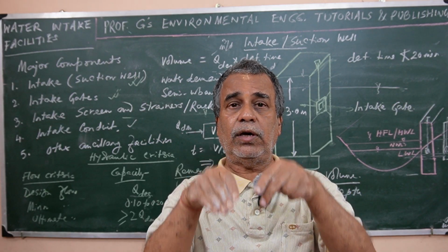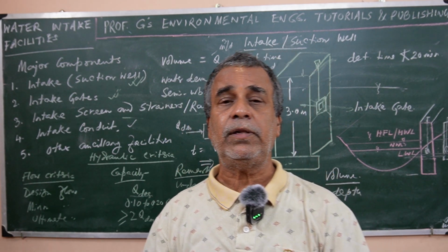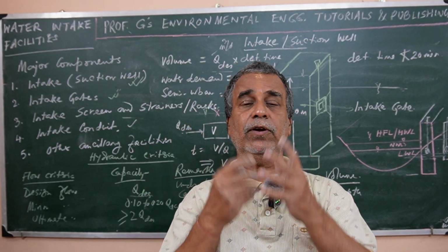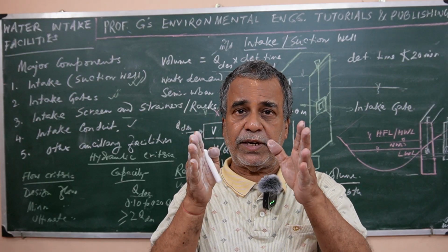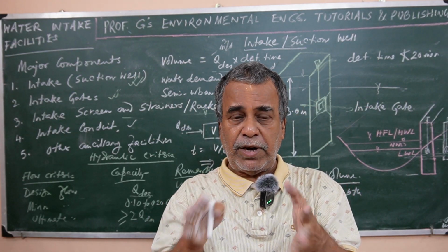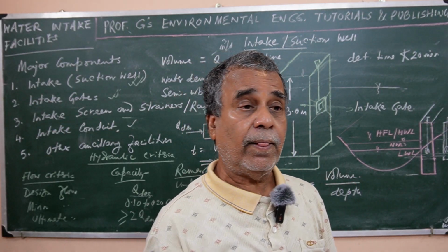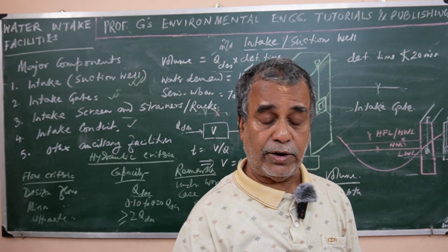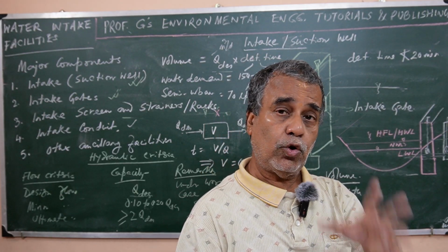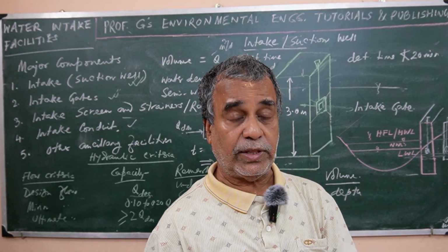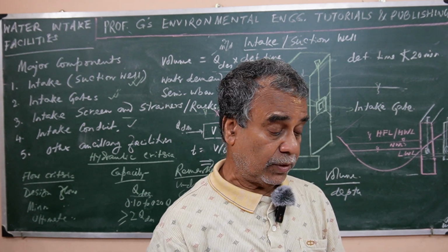So to safeguard against possible buoyancy or uplifting of the structure, the total weight of the structure must be higher than that. Remember this. Whatever structure you design, the concrete and RCC, you must check that the total weight is in excess of the uplift pressure.